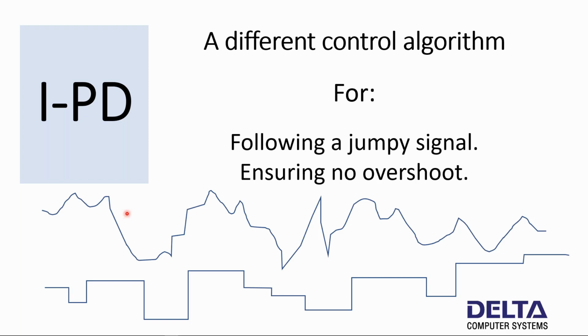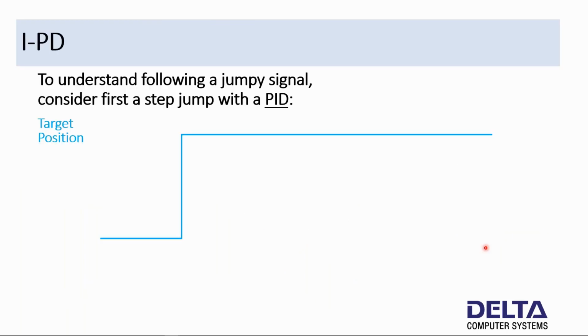So there's sometimes that you may have an old system that you're retrofitting and it sends out an analog signal that tells the controller where to go. And maybe you're just upgrading the controller, put an RMC in there, and you're stuck with this lousy analog signal that hopefully looks like a step jump like this, but sometimes it looks like this real messy one, and it's just a real challenge to follow exactly and control. It's much nicer when things are done digitally rather than with old antiquated things, but regardless, we have to do that sometimes.